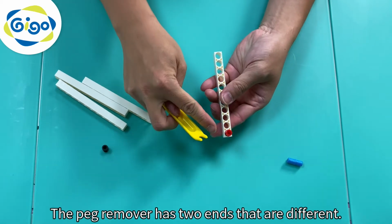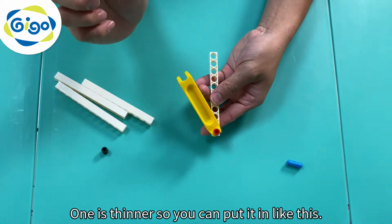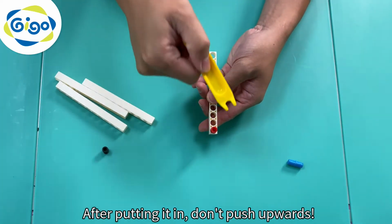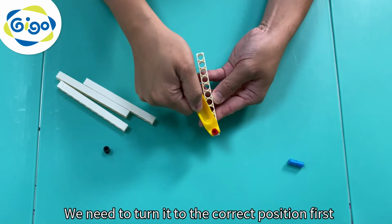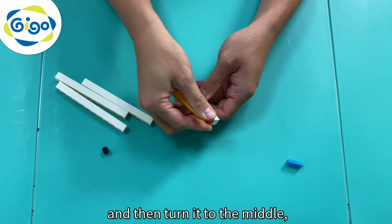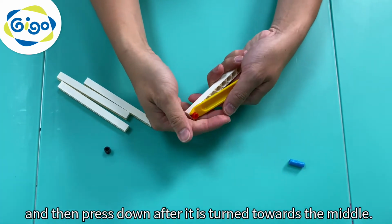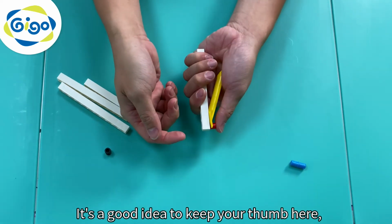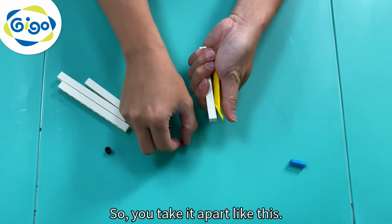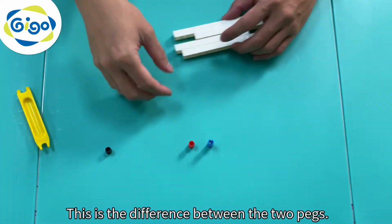The peg remover has two ends that are different. One is thinner, so you can put it in like this. After putting it in, don't push upwards. We need to turn it to the correct position first, and then turn it into the middle. And then press down after it is turned towards the middle. It's a good idea to keep your thumb here so components don't fly across the room. So you take it apart like this. This is the difference between the two pegs.